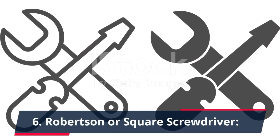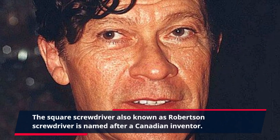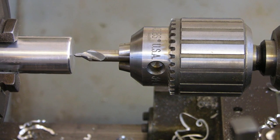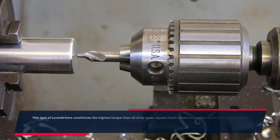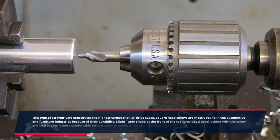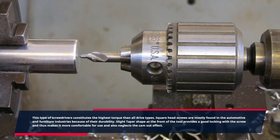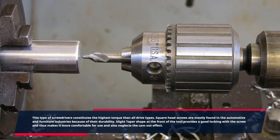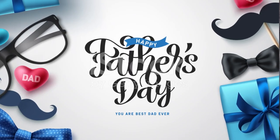6. Robertson or square screwdriver. The square screwdriver, also known as the Robertson screwdriver, is named after a Canadian inventor. This type of screwdriver provides the highest torque of all drive types. Square head screws are mostly found in the automotive and furniture industries because of their durability. A slight taper at the front of the tool provides a good lock with the screw and thus makes it more comfortable to use and also eliminates the cam-out effect.